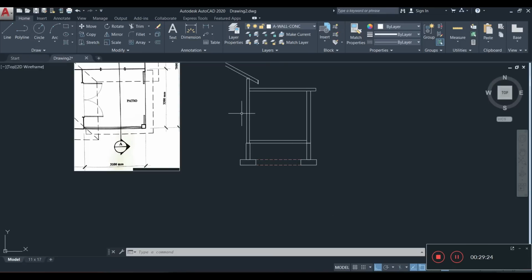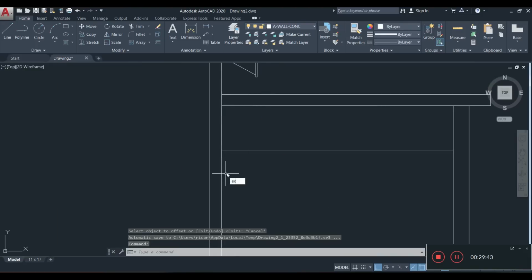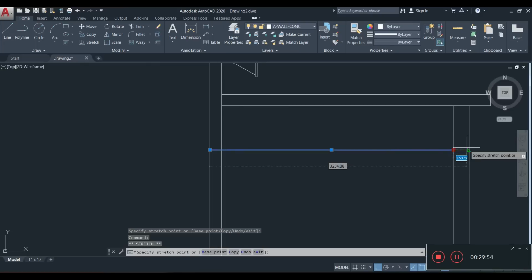So here we have window, so let's pop in that window. Using typical or what we did for SBA, the top of the window is going to be about 2100, so let's offset 2100 up like this. Alright, this line here will extend to here. Alright, I'm also going to extend it over here as well. All right, and you'll understand the reason next.